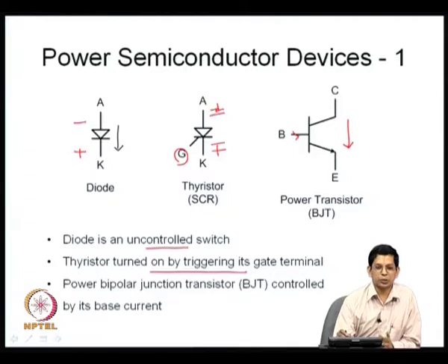So, this is also a switch now, it is a little different. In amplifier circuits you make the transistor operate in the so called linear or active region as it is called, whereas in power electronics you use this transistor such that the base current is substantially high, so that it is driven into saturation or it is in the on state, otherwise there is no base current, so that it is in the off state. You make use of it as a switch now. So, these are some important kinds of power semiconductor devices now.